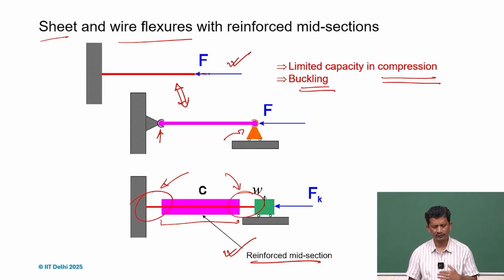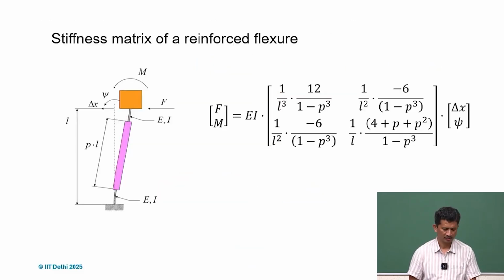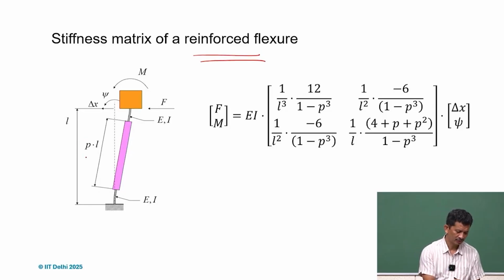Of course we want compliance, but at the same time we also want stiffness and load bearing capacity. How things improve or degrade, we need to learn that. Again we take a generalized case, for reinforced flexures, where there is a total section length and a reinforced fraction P.